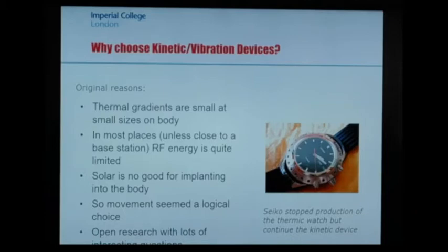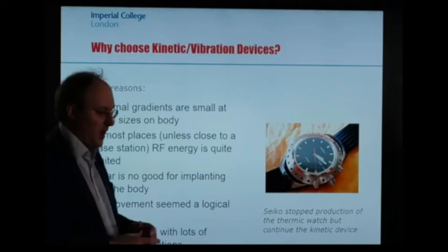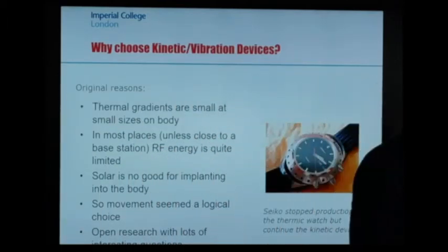We're not ever going to be in the situation where we have 5 or 6 off-the-shelf energy harvesting designs, because we're always going to have to tailor it to a particular application, because the volume is important, the constraints on the volume are significant. The vibration characteristic that you're going to be powering this thing off is going to have to be tailored to every specific application. Is it a fixed frequency? Is it a whole set of frequencies? Does that frequency change over time? All those sorts of things mean that actually producing a small number of harvesters in the same way that a small number of battery types exists is not something that we can do.